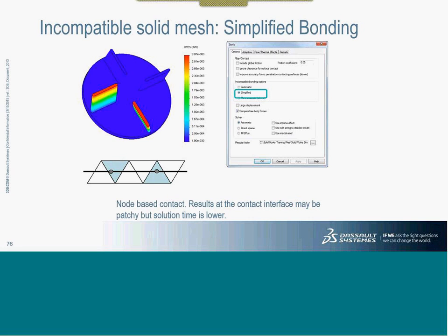And this gap that you are seeing, let me take the pointer, this gap that you are seeing here would increase or decrease based on the quality of the mesh between these two. Quality in the sense that one of the parts may have a very fine mesh and the other may have a very coarse mesh. Then obviously the connection should be lesser and lesser and things may be appropriate.